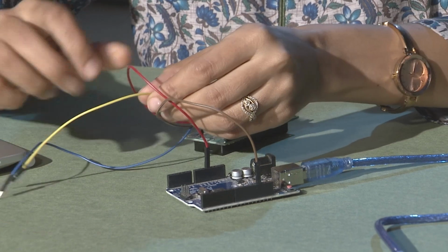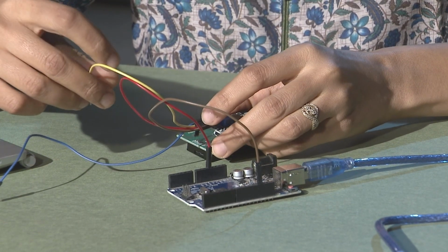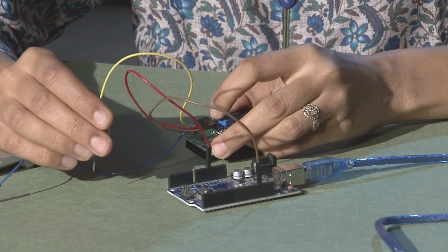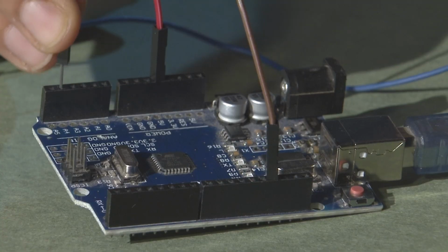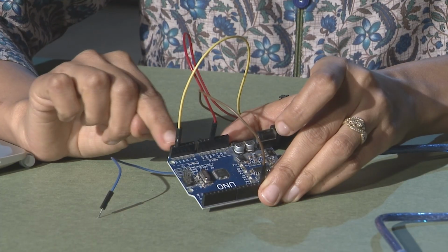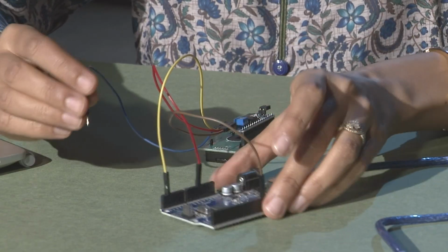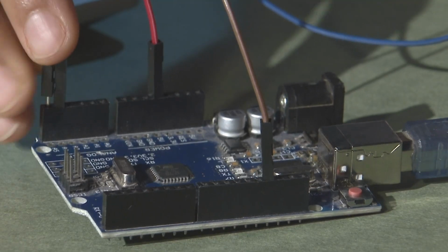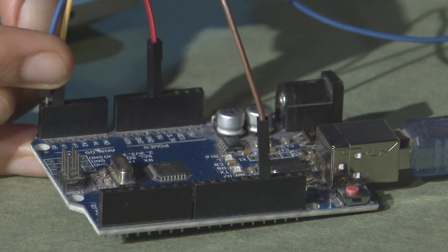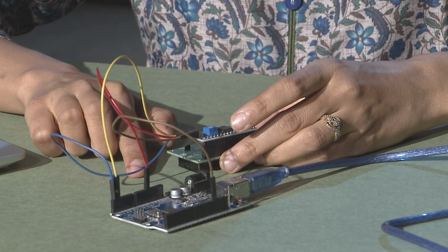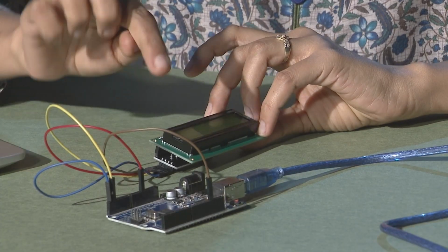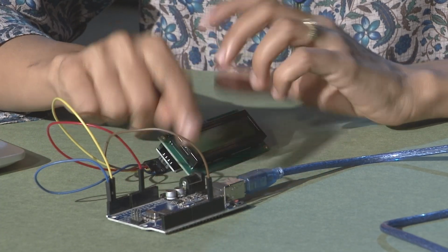Next to this we have your SDA line, which as per your circuit diagram we have to connect to the A4 pin on your analog port, and after this we have the SCL line, which will be connected to the A5 line of your analog port over here. So, these are your connections for interfacing the LCD board with your Arduino board, and now we need to understand the coding part for this interface. So, let us switch to the software part now.